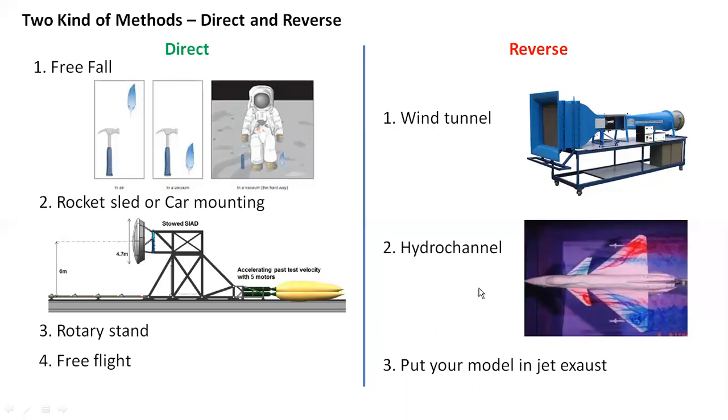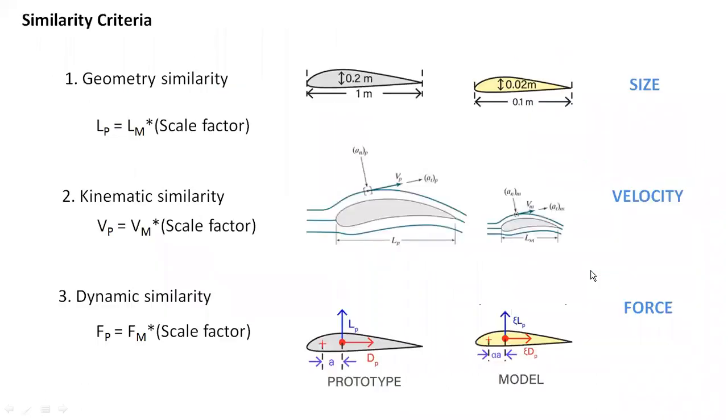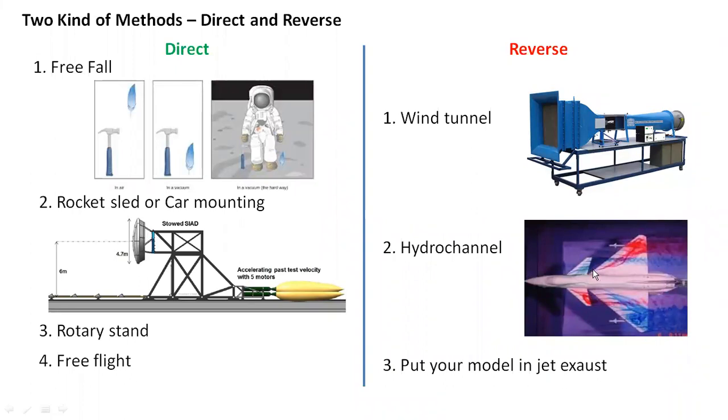Yes, liquid paint. This paint shows you flow lines of air. You can see a pipe vortex from canard. You can see a leading edge vortex from delta wing, and this helps us understand the complex structure of flow around a body.